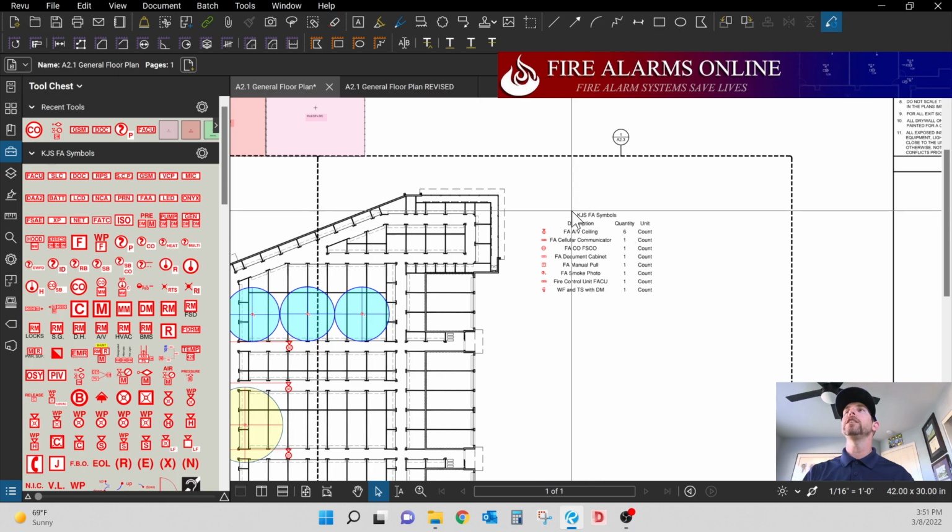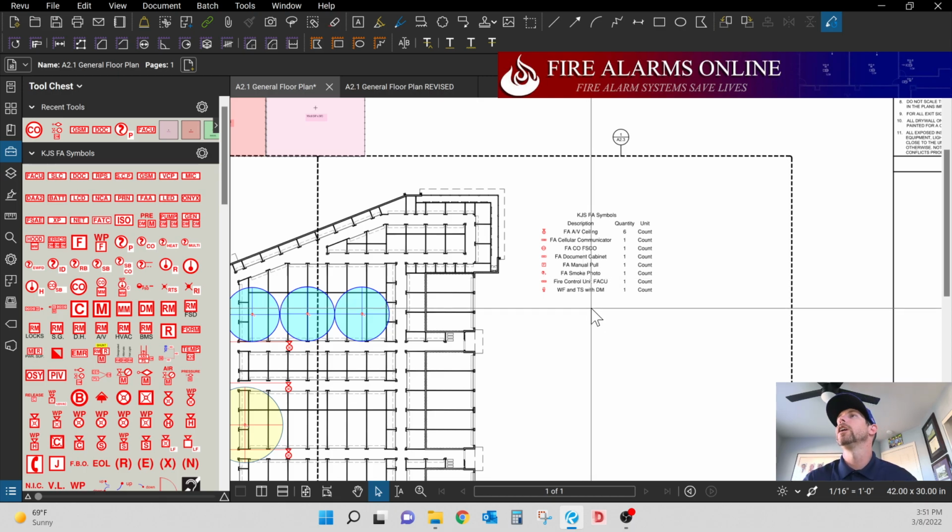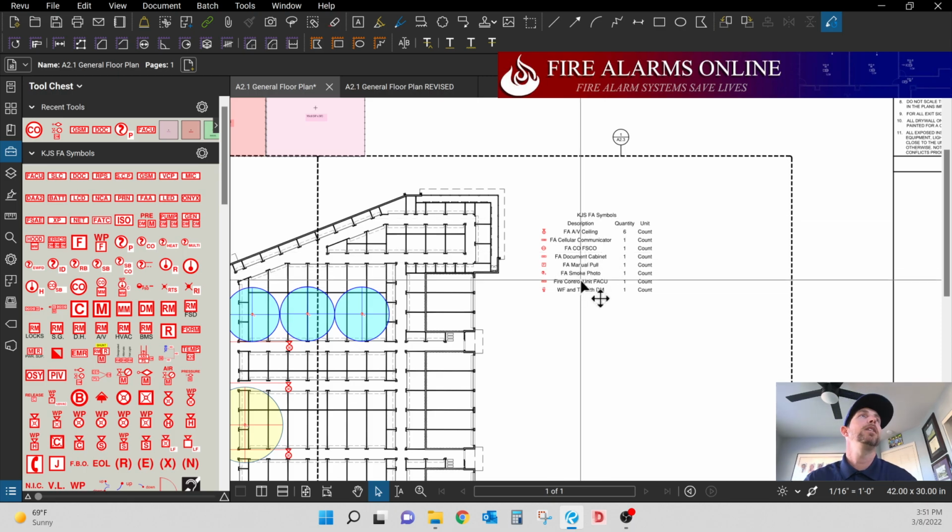This is something nice to put as an itemized list on every page for maybe the electrical contractor that's running the pipe for you, or your design team or your PM, so he kind of knows what he can do for his schedule of values or whatever he's going to do to gear up for each floor. There is a way in Bluebeam to do a total count of every floor and every sheet together, and I'm going to show you that next. But I wanted to make sure you guys understand that this is not for the entire document. This is just for this sheet.